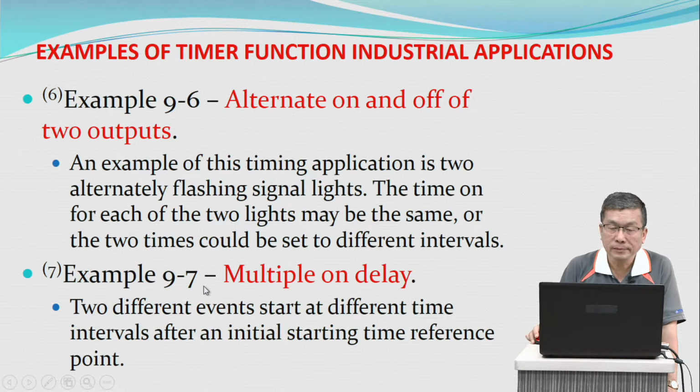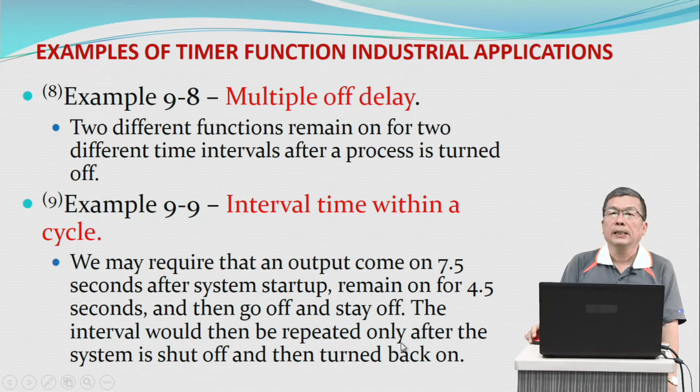Example 7. Multiple on delay. Two different events start at different time intervals after an initial starting time reference point. Example 8. Multiple off delay. Two different functions remain on for two different time intervals after a process is turned off.